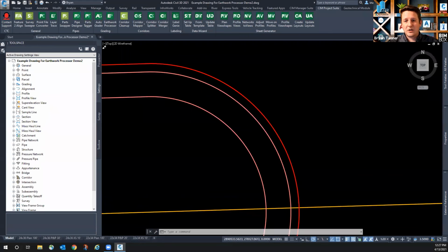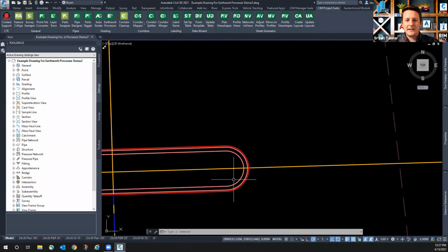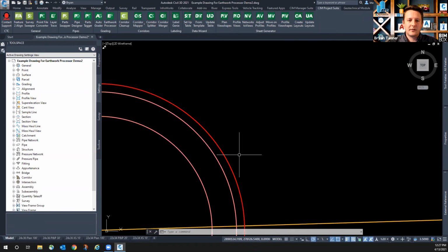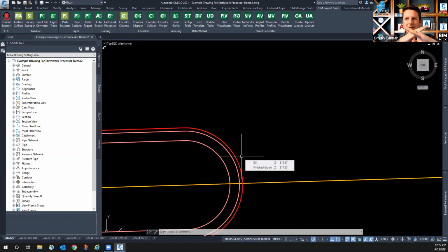But in general, whenever I have these type of curves, yes, 1/100th is going to get me the most accurate representation of a surface, but I want to use at least, or at largest, a 0.025 distance. Anything larger than that, you're probably going to chance your chord distances or your chords cutting across this arc intersecting with each other, and then you're going to run into some issues about where those vertical surfaces are.